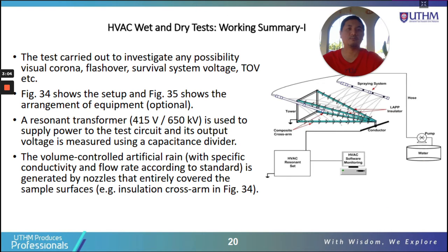The test is carried out to investigate any possibility of visual corona, flashover, survival system voltage, TOV, etc. Basically we supply high voltage, and we have to check if there is flashover or corona, to test the insulation, to check whether the insulation is designed properly and can withstand the voltage or not, and so on.